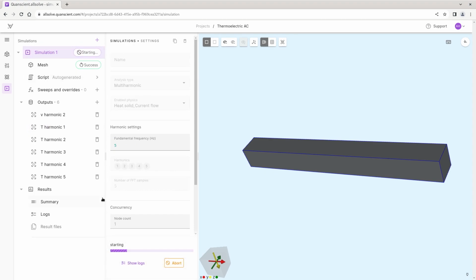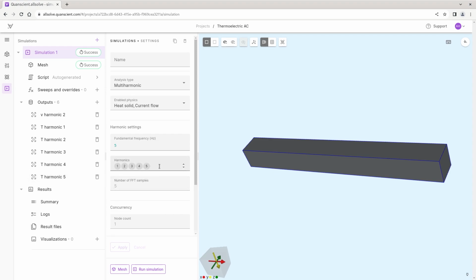And in terms of computing power needed, of course, for the temperature field, you will need 5 times the unknowns you would have with, let's say, a steady state static analysis. So computationally, this is more heavy, but the cloud is available to you. So the computing power is still largely enough for very large, tens of millions of unknowns problems on really complex geometries, even for nonlinear frequency harmonic problems.